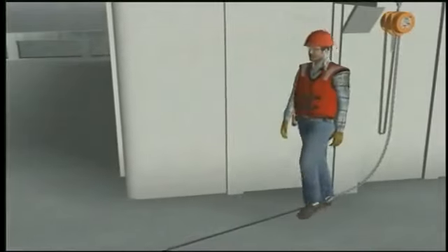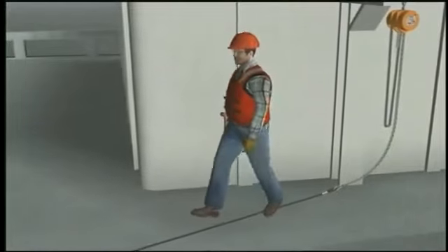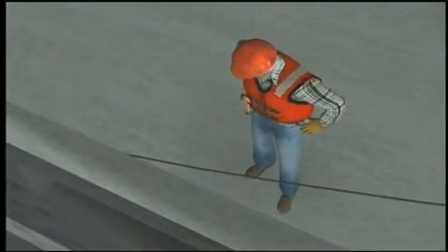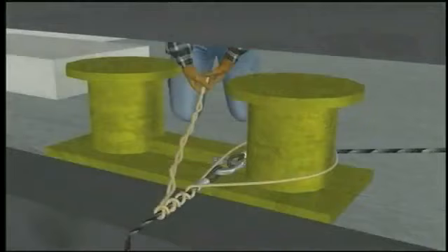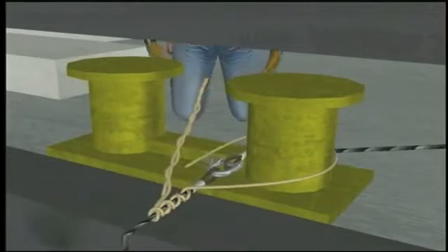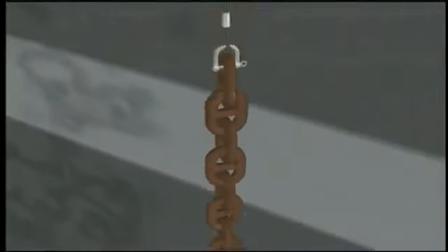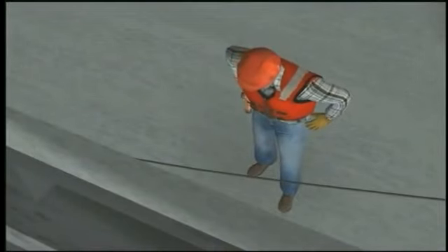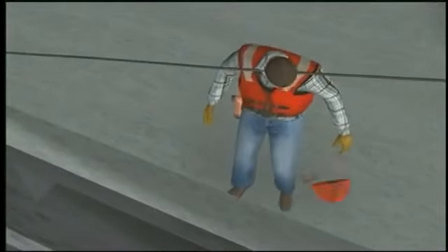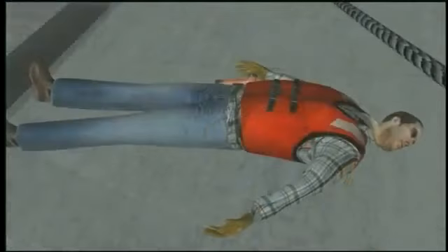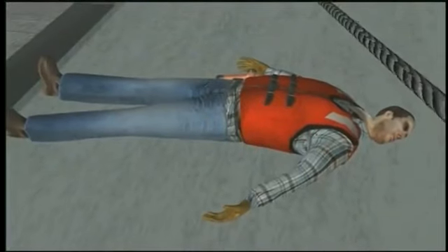While waiting for instructions, the worker walked into the area and looked over the deck edge to see what was wrong. The manila rope stopper snapped, causing the weight of the chain to be transferred back to the sling assembly. The slack assembly suddenly became taut and struck the rigger in the neck with tremendous force, breaking his neck. The rigger died instantly.